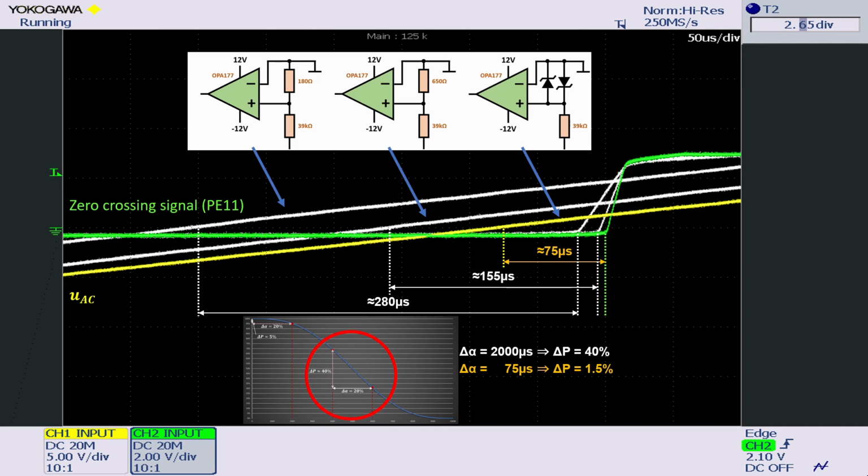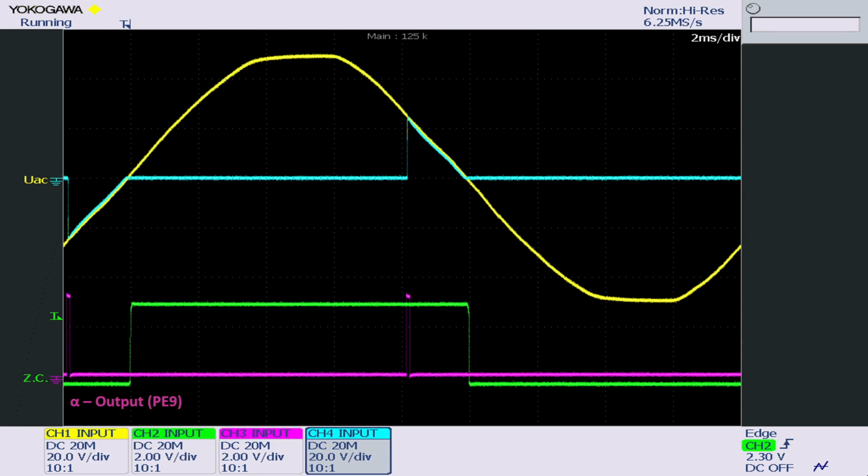Now let's continuously change the normalized output power in steps of 4% from 0 to 100% using our microcontroller program. 100% have been calibrated to dissipate exactly 50 watts in the resistive load. This has been achieved by fine-tuning the variable transformer output voltage. Let's start the program and measure each actual output power.